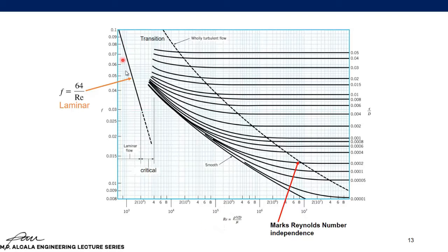So the laminar flow here is dependent only on the Reynolds number, from 0 to 4,000. Okay? This range is noted as critical from 2,000 to 4,000 because it is considered your transitional flow. But in here, it behaves linearly: 64 over Re. Okay? Next.